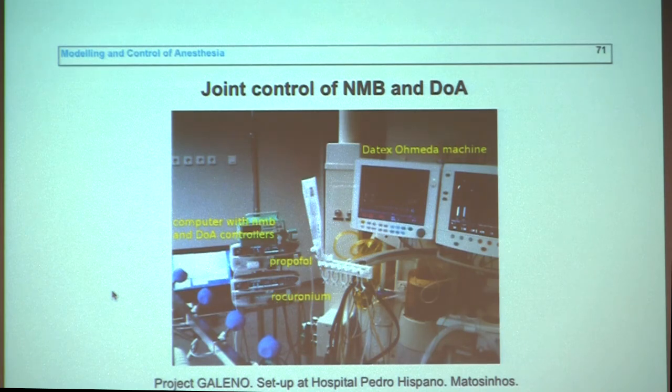Even if there are some variations due to noise or, for instance, the electric scalpel causing disturbances, you want to return to this value. So this is a regulation value. In this regulation value, essentially, you have a linearized model, okay? And you have uncertainty. So use some algorithm that allows you to control an uncertain nonlinear model.